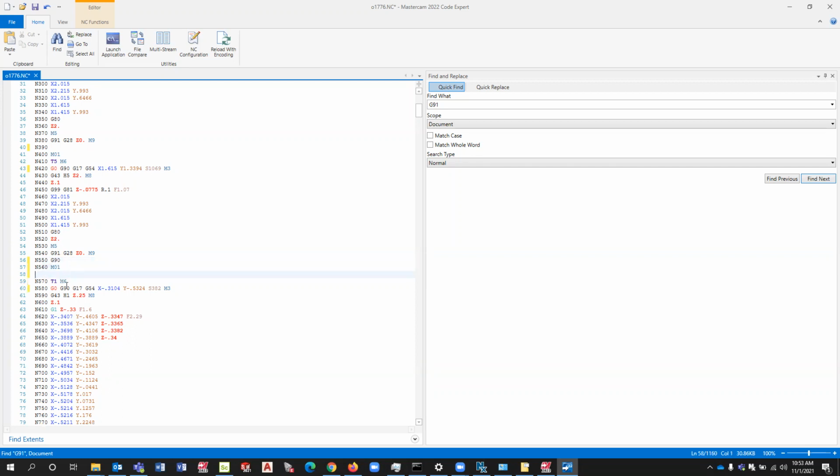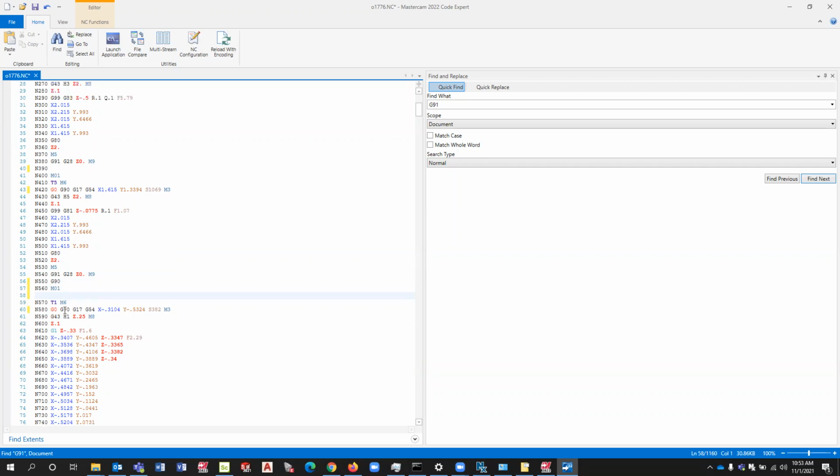And I also like to give it an extra space between all of these tool changes. Now, that's the forced tool change here. It forces a tool change and then a safety block before it keeps going on. And that's good if you stop the machine or if you have to pause it during the night and then you start back up in the morning on the next row, then you have all this information and it does the safety codes without any problems. If somebody ran something between everything, you don't have your safety codes, and there might be a problem.